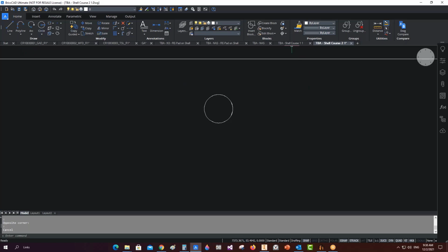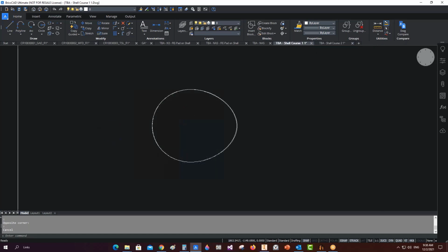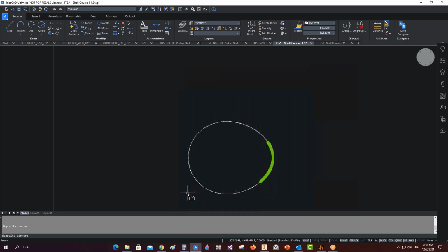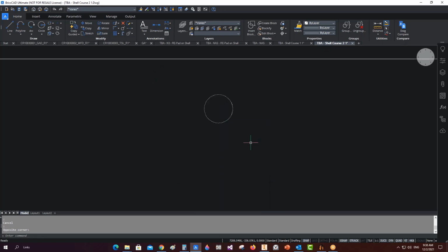What I'm trying to say here is not about the entity type in AutoCAD. It's the shape, basically. Whenever the opening is on a cylinder and you flatten it out, in this case we see that it is like an oval, right? Not a perfect oval, because it is on the side, or it is a tangential nozzle. But whenever it is a radial nozzle, in that case also it should be like an oval, right?